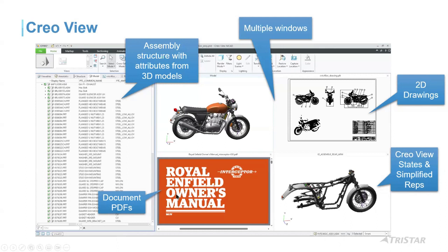And I can interrogate and search for parts that are of a certain material. I can search for parts that have a certain name. So if I'm looking for an M8 screw, or if I'm looking for some kind of an ISO manual or some SOP manual that I've associated to one of these standard components, I can see this information in the window and interrogate it.